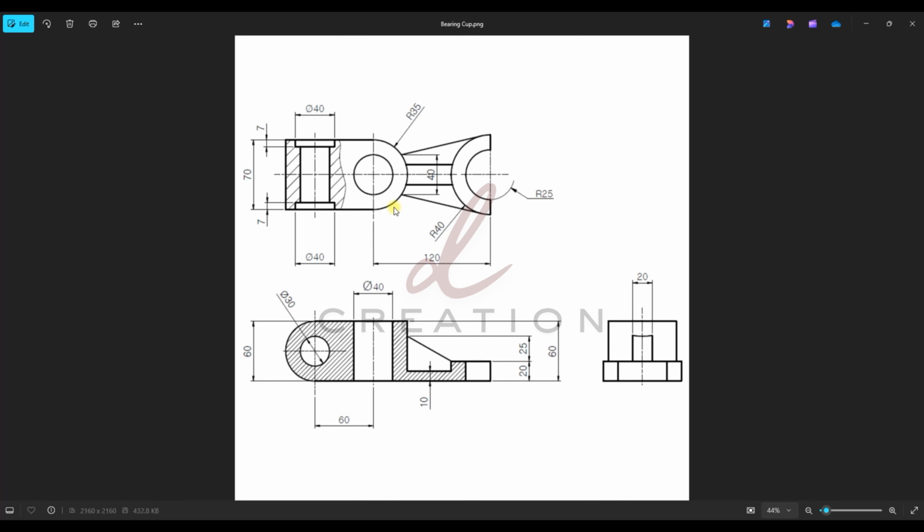So when we break down this detailed drawing, first of all we are going to create the circle at the center of origin, and then we are going to create this circle part attached with this circle, followed by using the contour feature to create this hump, and finally we are going to create this rib, as well as the hole using cut extrude. Here we can see that the hole has a counterbore or countersink part like this. So let's begin with the drawing.